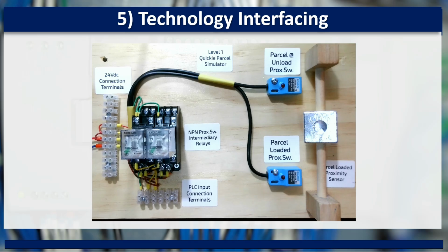You are looking at a model I built to demonstrate the principle. The metal-covered block triggers the proximity switch. Once triggered, the power turns on a relay, which has an input running through a set of normally open dry contacts. When the relay is energized, the contacts close, completing a wiring circuit to a PLC's input terminal.